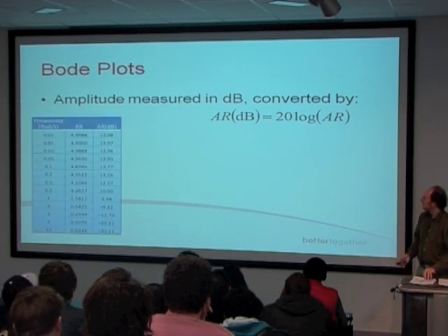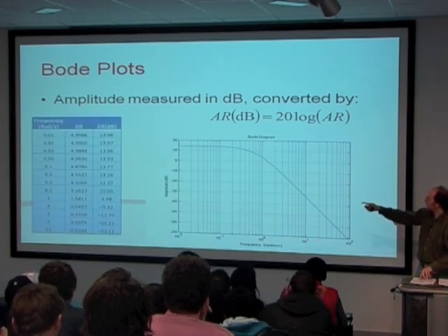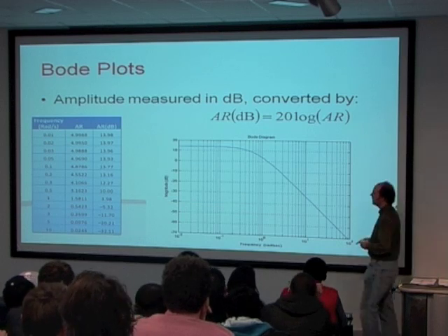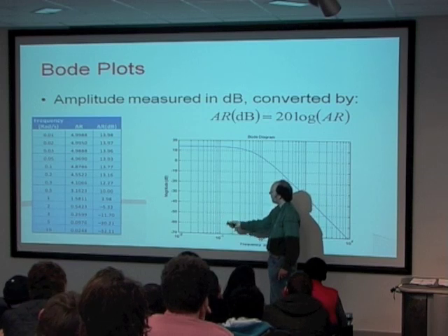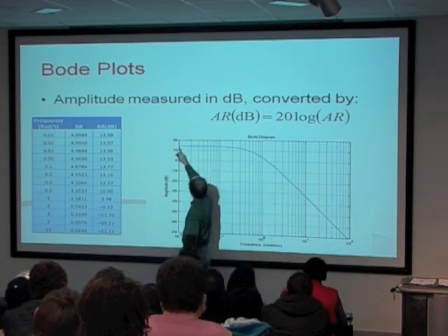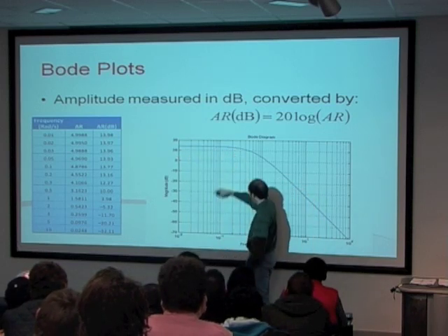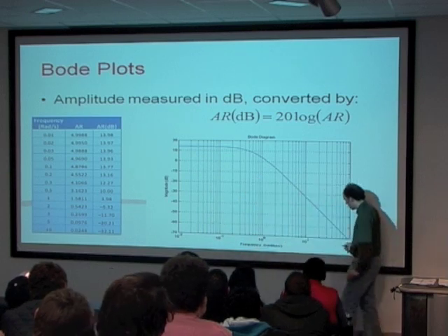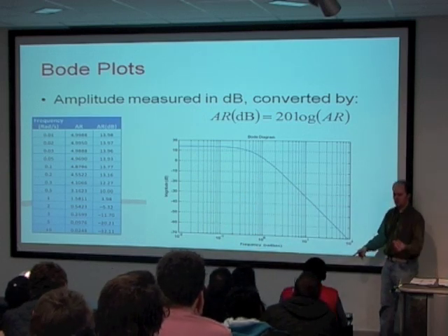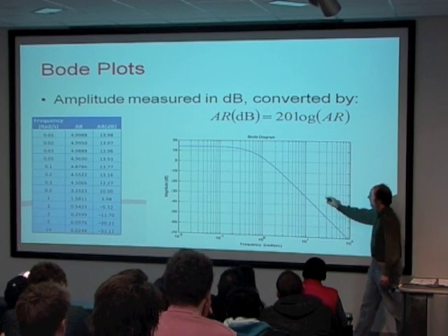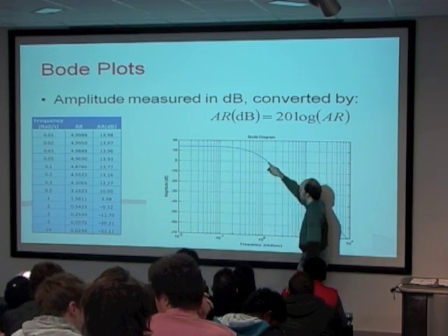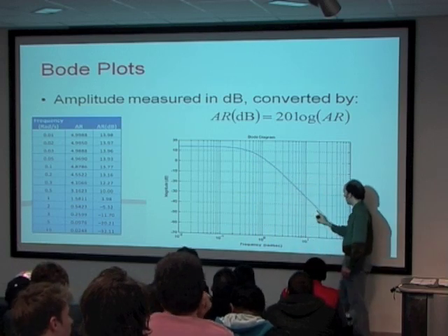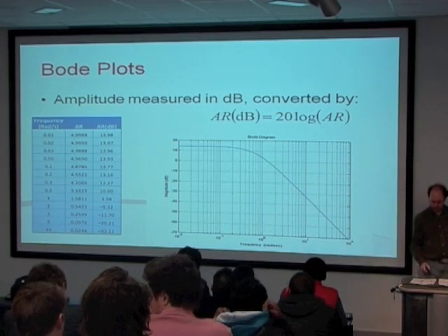And so, with that example, we've taken the amplitude ratio and you can convert from that to that, and that is what we've plotted. So we start out at about 14, and we come along, and then as the frequency increases on a logarithmic scale, notice why I did the logarithms there, the amplitude ratio starts to drop. At this point it crosses 0, and then it starts to be negative.